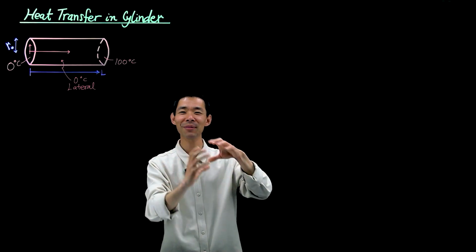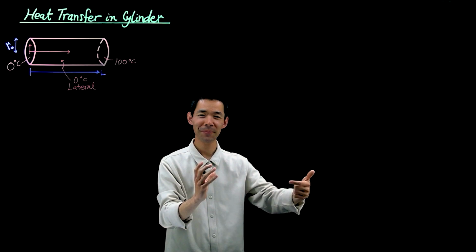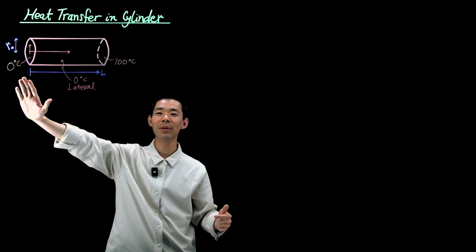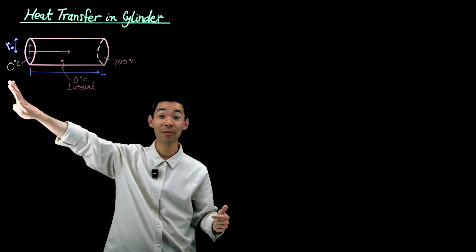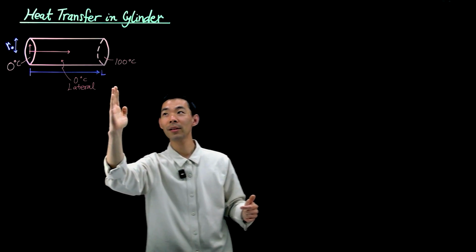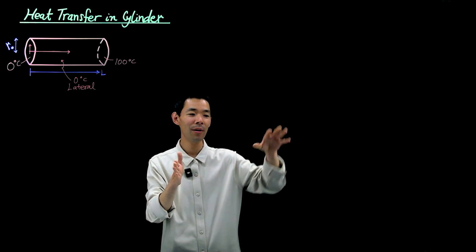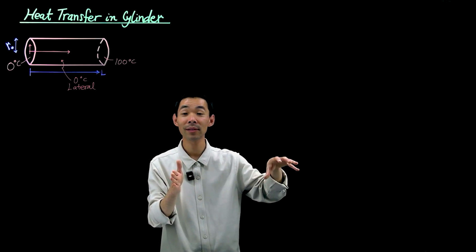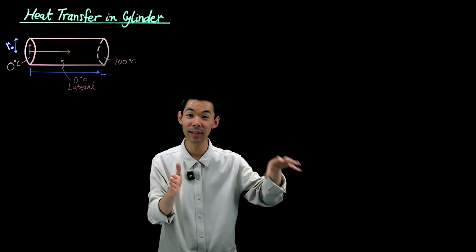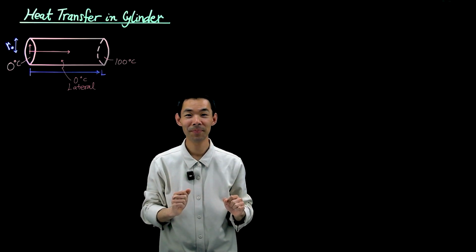Let's suppose I have a 0 Dirichlet boundary condition along the lateral surface. I have a 0 boundary condition also along the left-hand boundary at this position here. And then the right-hand edge of this cylindrical piece of material is subjected to boiling water, so 100C. Okay? Those are our boundary conditions.